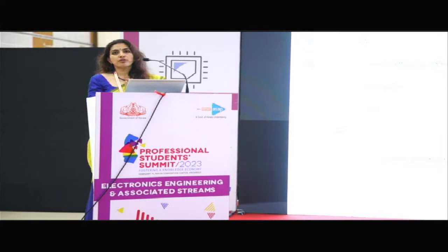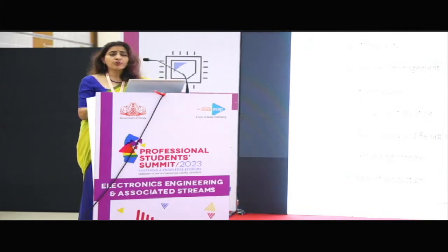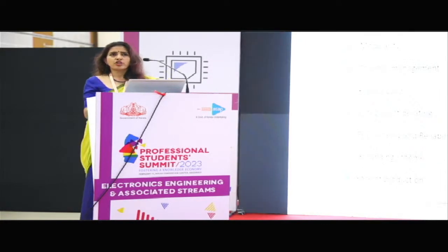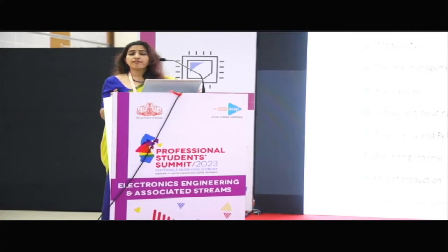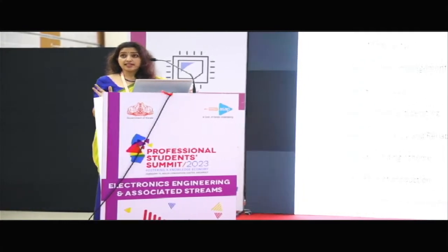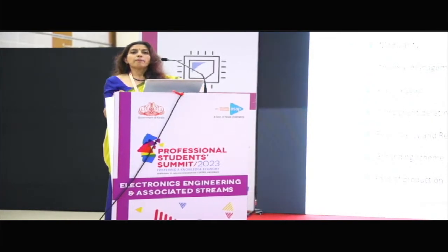And of course the power to mass ratio should be very, very high, otherwise it will be very difficult to fly in the spacecraft. Now the design considerations, it is purely power electronics term. We have to design on the topology. There are so many topologies, push-pull topology is there, full bridge topology is there, and ZVS, ZCS topologies are there. You might be knowing some of them, but we have done with ZVS, ZCS topology, and it's very, very crucial for the design engineer to select which topology that you should choose to get the maximum efficiency possible. And you have to manage high voltage and high current also with all these restrictions. And that is another challenging part.